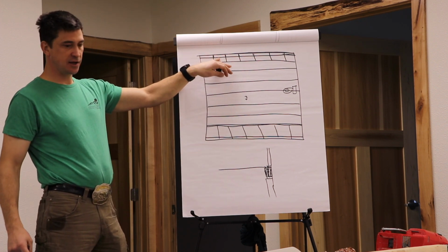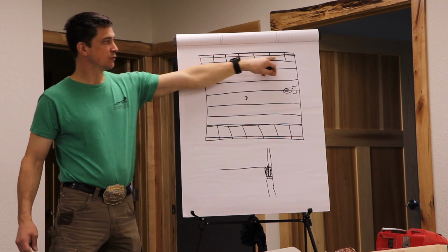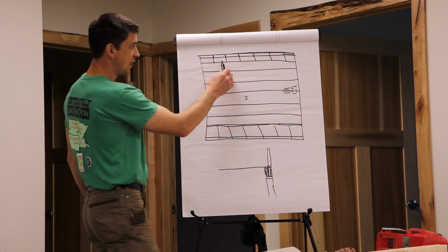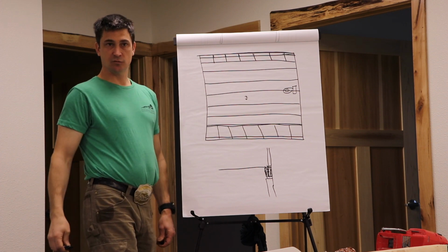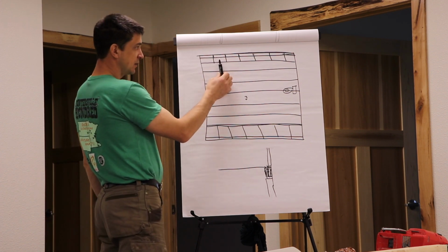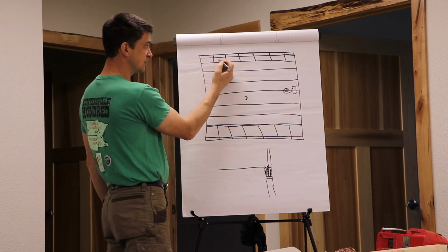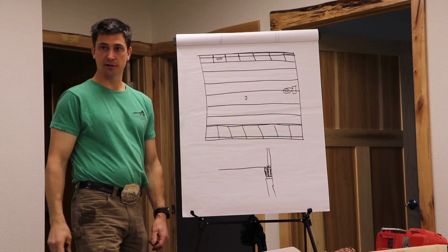It's not able to distort that floor system because it's supported with blocking that goes all the way down to your sill plate. Two, it gives a wide open space for your electrician to run his stuff into there. It gives a nice open space for your HVAC guy, because he's going to want to cut his holes in the floor and get his ductwork up in there.